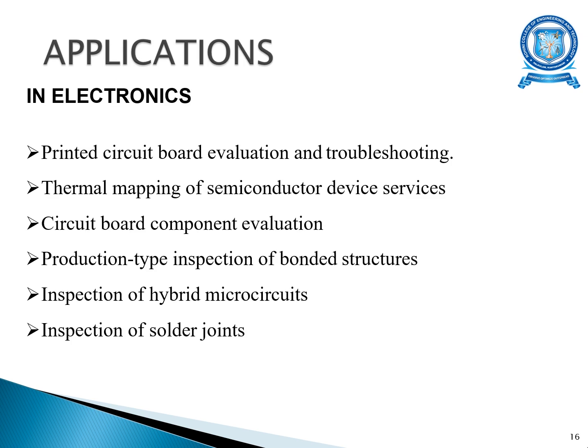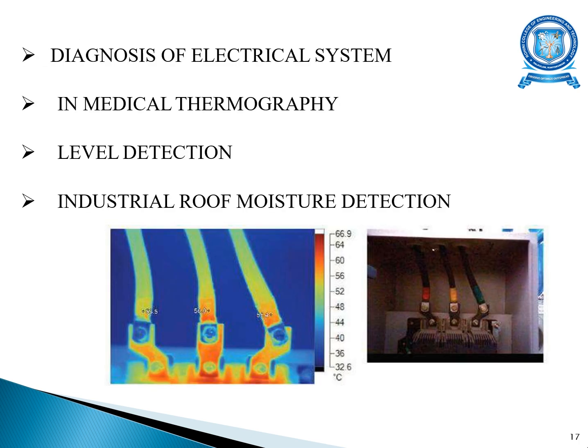So applications: in electronics, printed circuit board evaluation and troubleshooting is done using thermography testing. It is used in mapping of semiconductor device surfaces, circuit board component evaluation, production inspection of bonded structures, inspection of hybrid microcircuits, and inspection of solder joints.